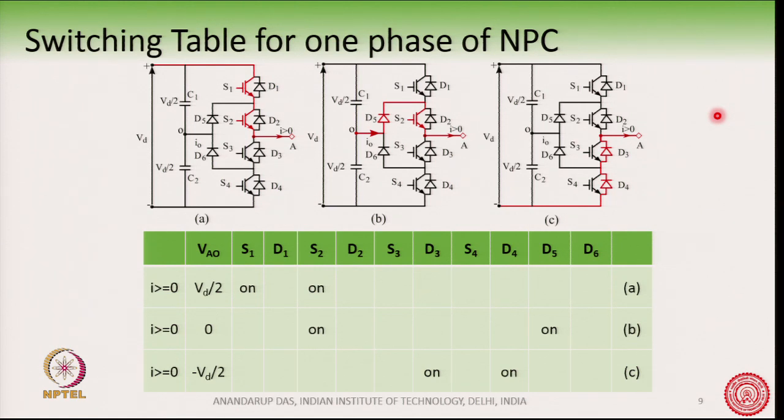So we understand that in this converter, all these 4 IGBTs or transistors, or MOSFETs if you use MOSFETs, as well as the 4 diodes are useful, together with D5 and D6. Under different conditions of operation, one or more switches will be conducting, and you should be able to fully understand under what condition which device will turn on.